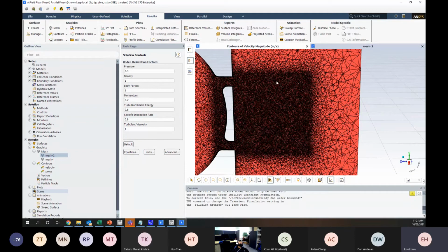So there's a turbulent structure size that is consuming the most turbulent energy. So our mesh size should be based on the size of that turbulent structure, some function of that, rather than our mesh independent study in the traditional sense.